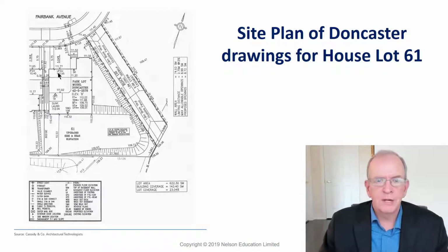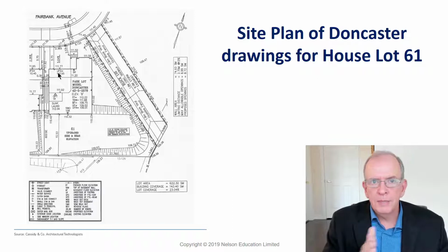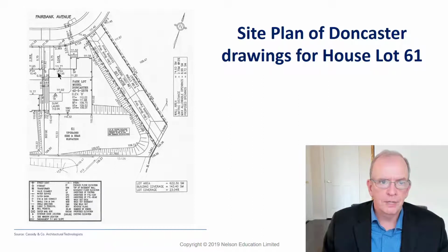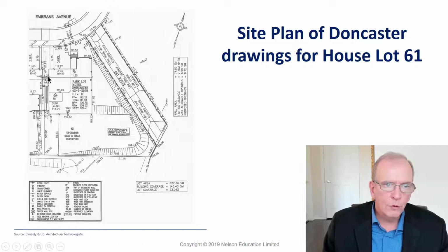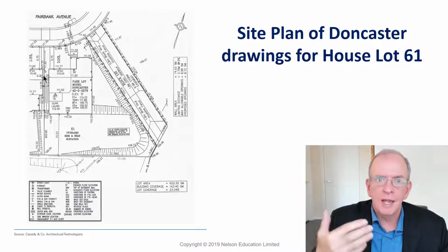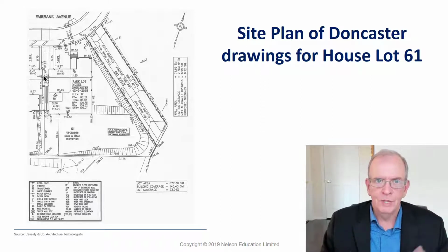If it's a townhouse, it's got fire separation requirements and firewalls. If it's a single house next to another single house, we've got limiting distance requirements, which limits the size and the amount of area of windows depending on how far back the house is set back from the property. So one house is typically going to be more than 4 feet, while the other is going to be less than 4 feet. You can do it obviously more as a builder developer, but then that limits your footprint to build the houses. So that would mean you've got to build smaller houses. Maybe that doesn't tie to highest and best use, providing the best value to the builder when they sell it.